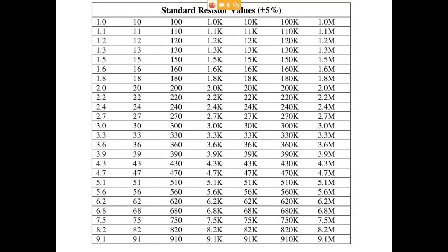So you see, let's say you wanted a 4,500 or 4.5 kilo resistor. Well, you could buy a 4.3, and then you would need a 200 ohm, and put those in series, and that would give you the amount of resistance that you need. But we also have to worry about the tolerance. I mentioned that fourth band is the tolerance. The tolerance is how much it can vary.